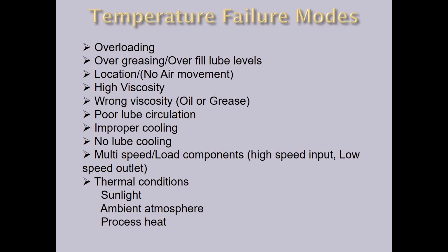Sometimes I've seen systems that have lube filtration systems on there, circulating systems, and the filter's partially plugged. Or there's some line restriction, and we're creating higher temps. Improper cooling, or no lube cooling. Sometimes we have to add a cooler, or sometimes the cooler we have on there is dirty, and it's not getting good airflow, so if we don't have proper cooling, we're going to have high temperature.